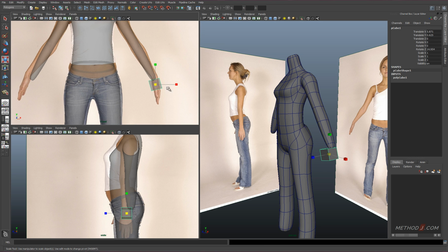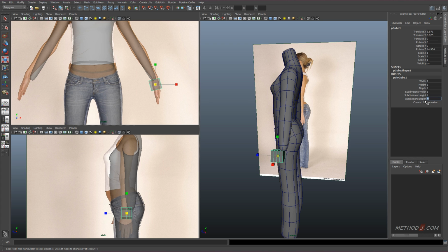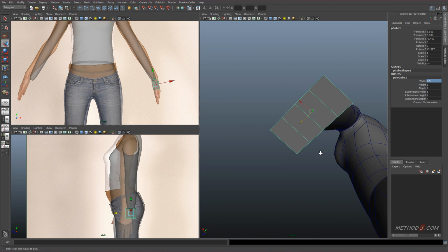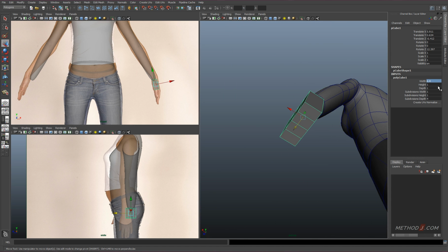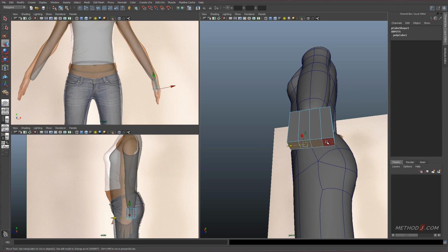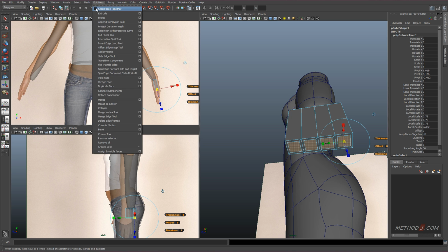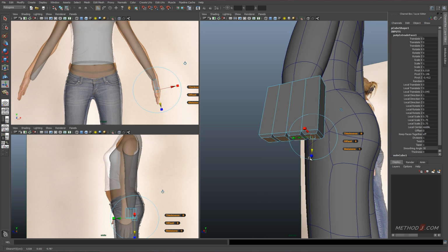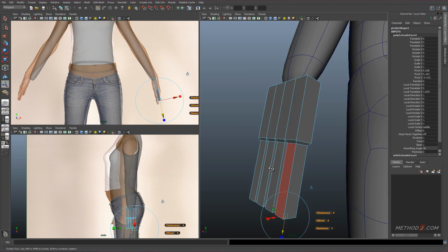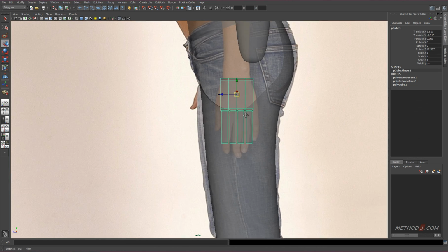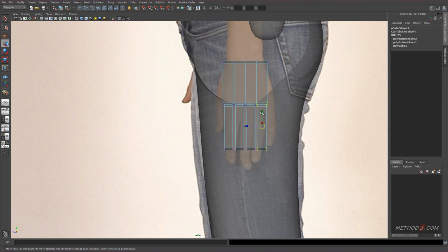The hands start as just a simple cube, and I'll add some subdivisions to the shape of the cube. And we'll do that to correspond to the fingers on the hands, so we'll have the 4 subdivisions across. And I can extrude those faces out. When I extrude these, I want to make sure that I turn on the option to extrude the faces separately in the Edit Mesh window. And I'll just extrude the fingers straight out as just cubic shapes.